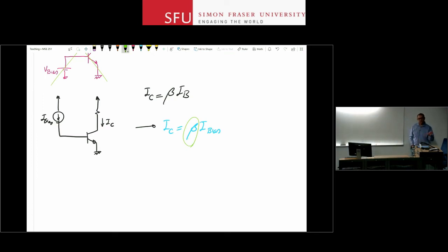And you have another problem here, similar to the one that we had before. In the previous situation, we had the problem of getting a very accurate power supply or voltage source. In this situation, the question is how do I get a current source? I know voltage sources exist in nature, right? You can use a battery to produce a voltage source, although they don't give you all the voltages that you need, so we have to figure out something there. I don't know of basic current sources that I can use here.